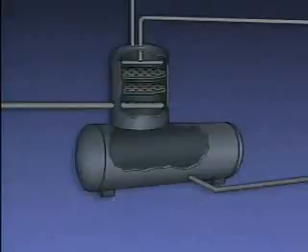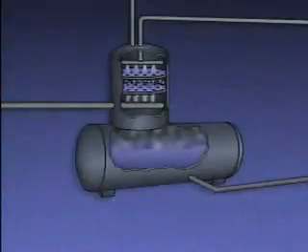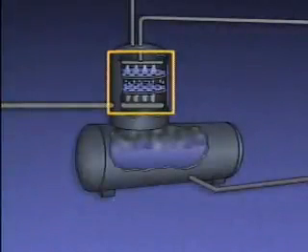In some circumstances, water containing even small amounts of dissolved gases may lead to problems such as corrosion. One piece of equipment that's used to remove dissolved gases, such as oxygen, is a deaerator. During operation, water is sprayed onto trays in the deaerator that break the water up into small droplets. Steam is fed into the deaerator, and the water droplets are heated as they cascade down through the trays.